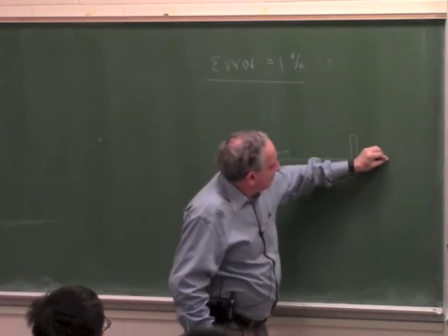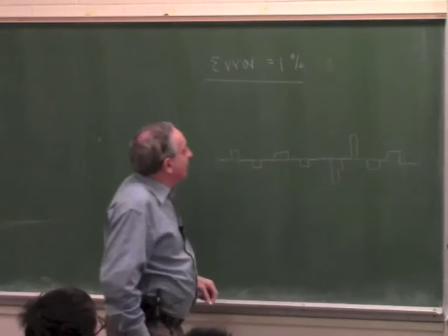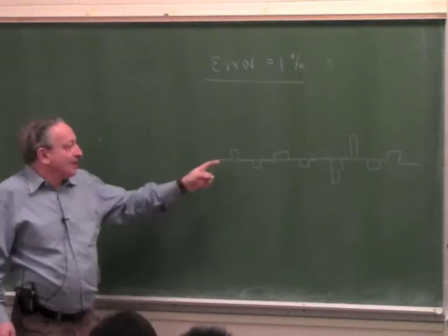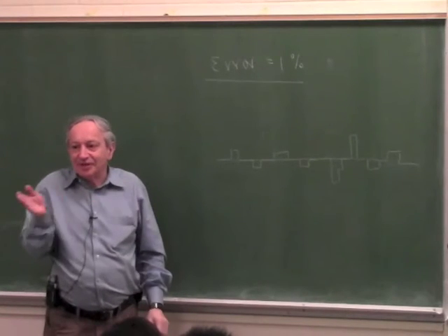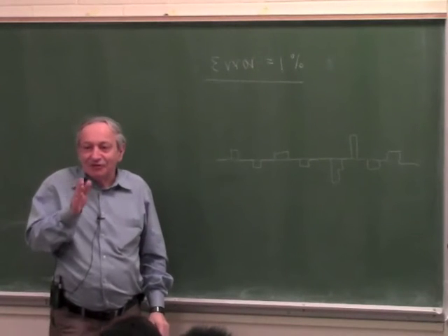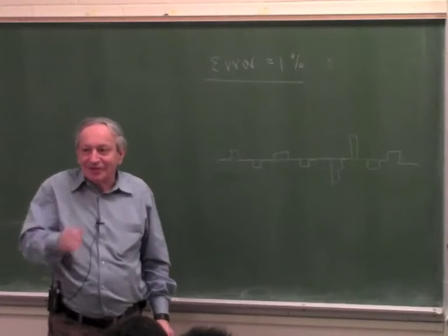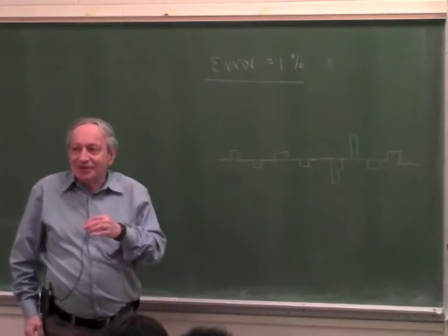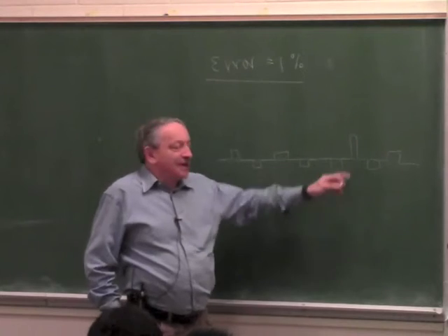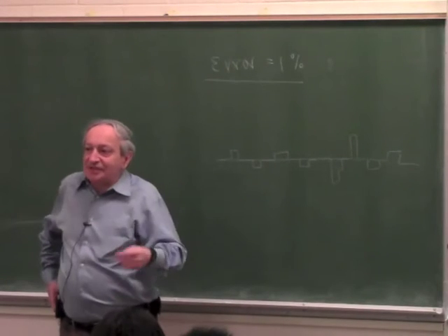So when you look at the output of a digital servo, at best it will be plus minus 1 bit, because it has to hunt, and because you can't fall exactly in the middle of a bit. When you are between 2 bits, it will hunt plus minus. But actually, most of the time, it hunts 2 bits, because of delays and things like that.